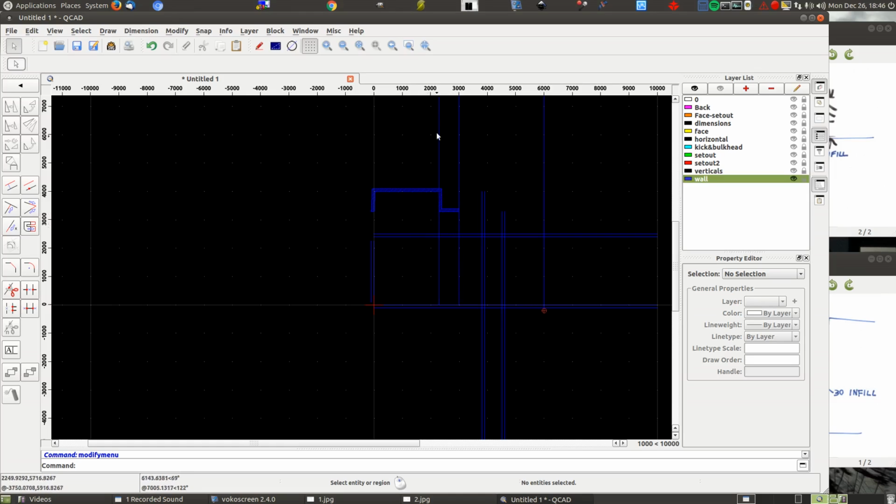Now these lines here I don't want to keep here anymore. Above this line I want them to terminate. So I'll use this tool, which basically shortens or lengthens. It says down here, choose limiting entity, which will be this line. If I click on that line, it'll stop there, etc. I'll just actually do that just to get some sanity here. They won't be the final terminations, but I'll do the same on the bottom.